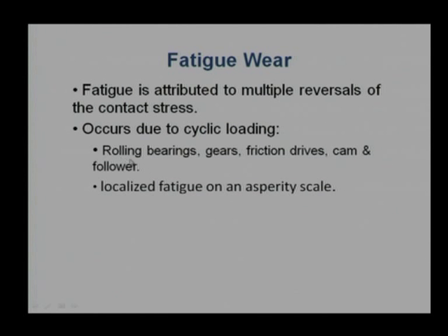We have a number of examples related to fatigue wear. It is a common phenomenon in rolling bearings. That is why rolling bearings have a definite life, which is generally calculated based on fatigue theory. Similarly, in gears, contact wear really governs gear failure. We know very well that gear failure can be estimated using two theories. One is the bending theory, the other is the contact stress theory or Hertz theory.